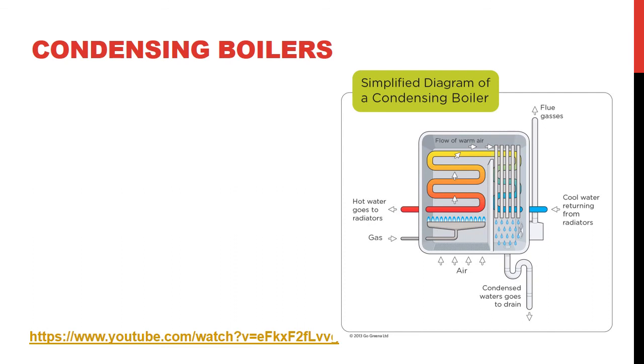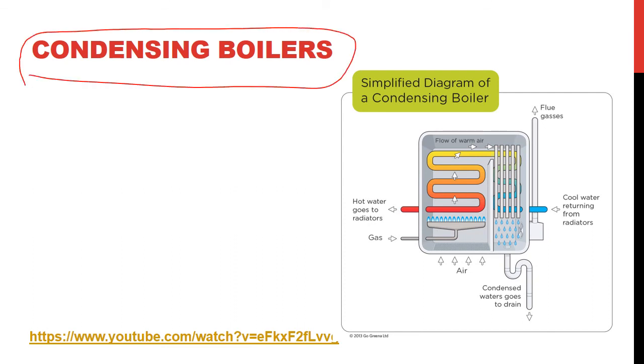Okay. Condensing boilers. I have a video about condensing boilers and how they work. I put the YouTube link in here, and I'll also put it in Blackboard. It's very, very interesting to watch. Again, most of the new systems are condensing boilers, and we want to keep those. We want to update to condensing boilers because they are very efficient. We can achieve thermal efficiency up to 97 or 98%, and it will be really worthwhile for you to watch the video and see how they work to get an idea if you will have to install these.